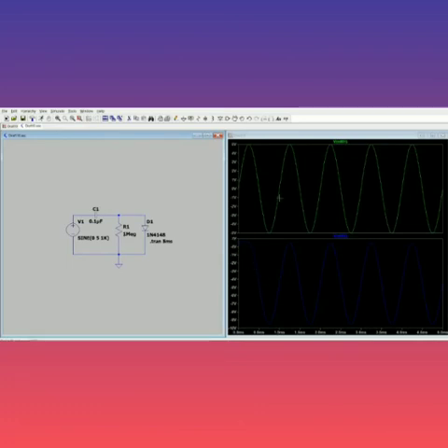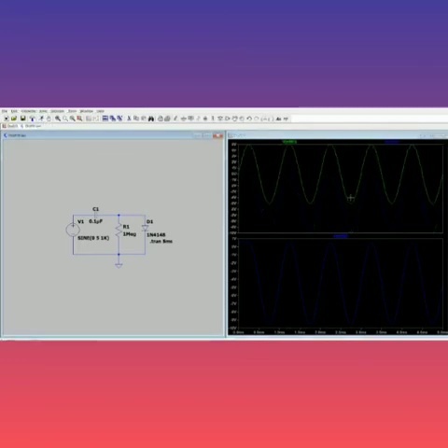So I can show this also in the same thing. So click it in the first input position itself. Then again go to your run option. Keep your cursor near the diode. It will be coming here. For your better understanding, this green color is your input wave and this blue is your output wave. You can see that it is clamped in the negative side because this is a negative clamper circuit. So it is clamped in the negative side to 2 VM, that is 5 volt is being clamped to 10 volt. I hope you understood.